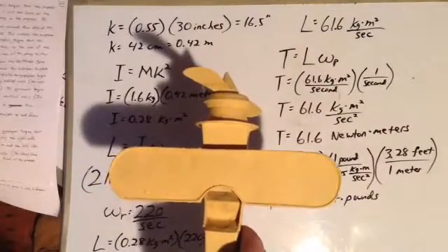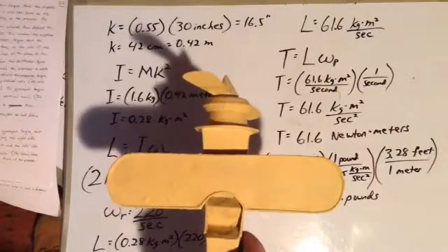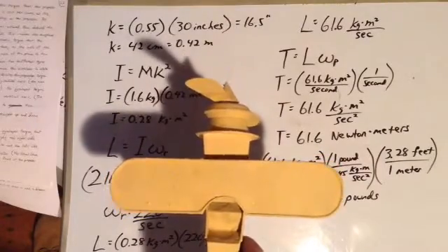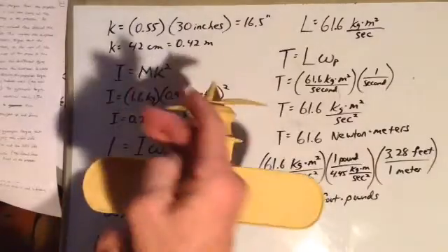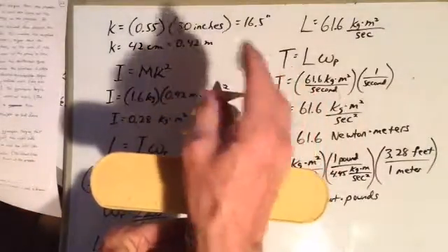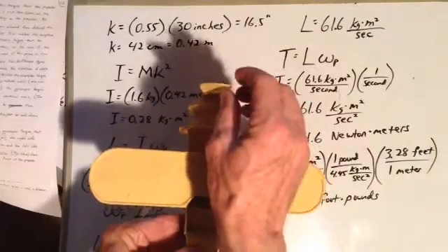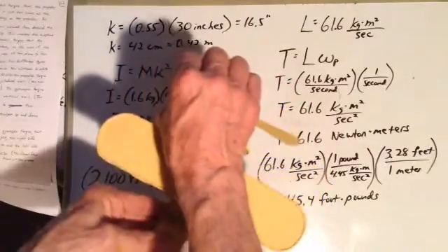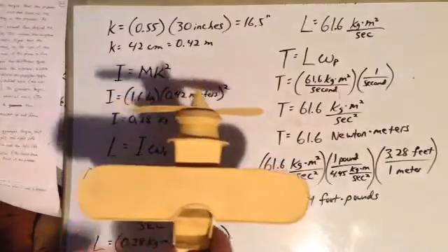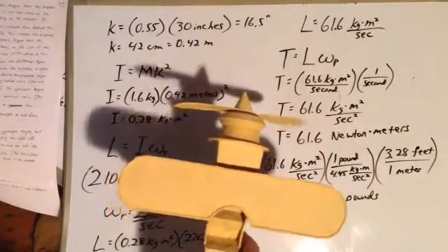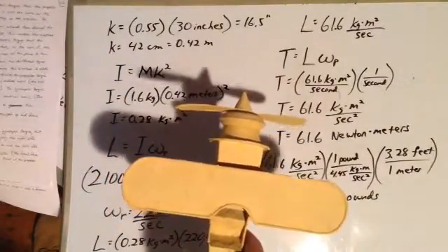Okay, the gyroscopic torque that the propeller would exert on the airplane as the nose of the airplane drops: if we're spinning along counterclockwise and the nose just drops, that's just like pushing forward on there, so it'll go over that way. It'll make the nose tend to turn to the right.